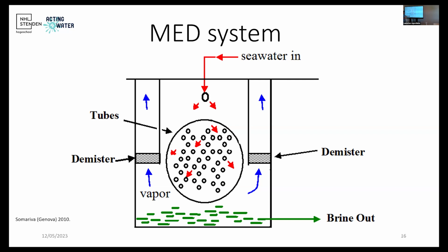Where does this vapor that passes inside the tube bundles come from? Well, it comes from the evaporation in the lowest stage of the collected brine. So the fraction which is not used and evaporated for the formation of the brine deposits and then creates a new vapor, which will be redirected to the next tube bundle condensation step, and will form your eventual distillate.